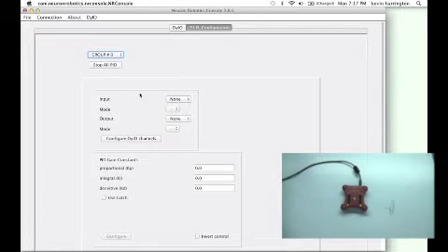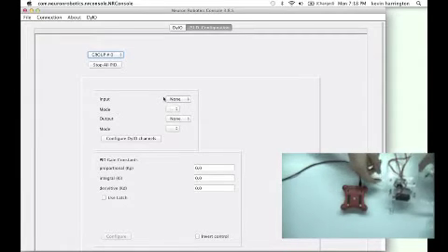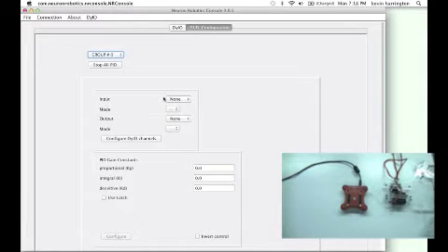To start with, you select which DyIO channels you want to participate in this PID controller. For more information on what a PID controller is and what math governs it, please see the attached link. The first stage is to select an input. For our purposes, we're going to be using the Neuron Robotics Quadrature encoder, as demonstrated by our Ackerman Steer robot.